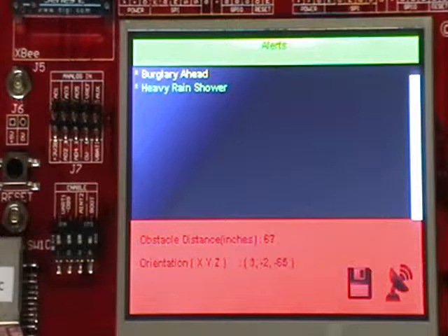So the mobile unit always pings around the environment to see if there's any beacon, and if there's a beacon, it homes in, and so you see that satellite sign solid during that intermittent connection that it can create. Since these are low power devices, these devices go to sleep, so you should see loss in connection at different times. But once a packet is sent, it's a pretty reliable setting, so you could pretty much guarantee that the packet would go to the beacon and from beacon back and forth.